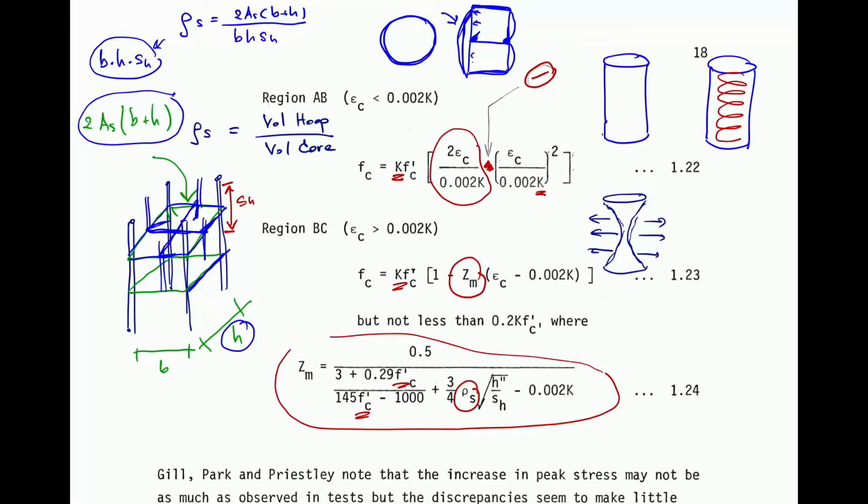So if the problem is the tensile stress that makes the system non-ductile, of course we know that under tension concrete is very bad in ductility. So the spring over here, the hoop reinforcement, will secure the surrounding concrete, and then the failure will turn out to be in this shape.